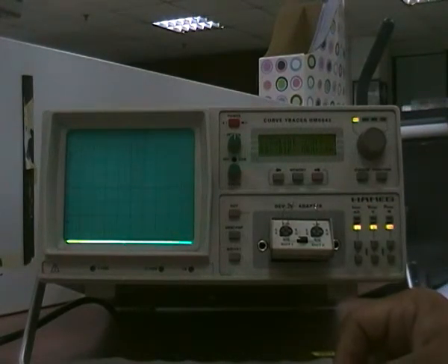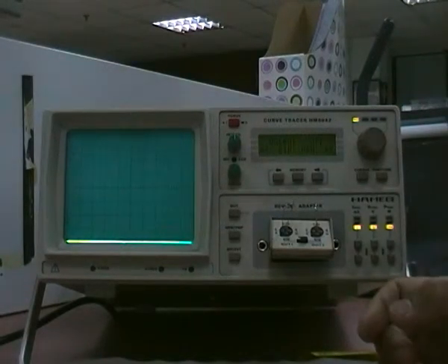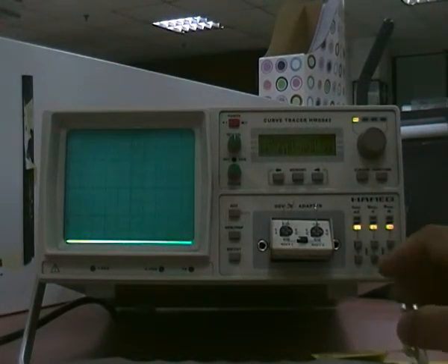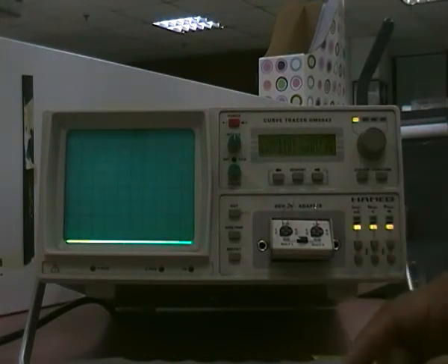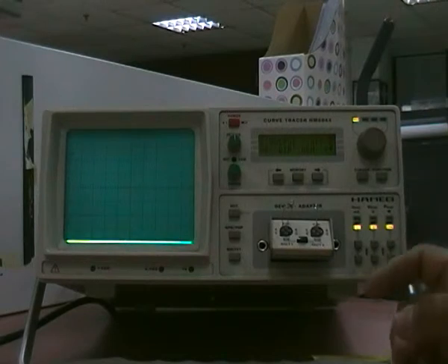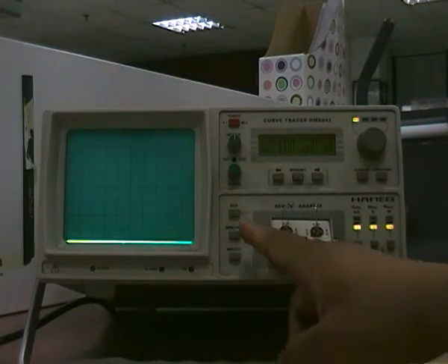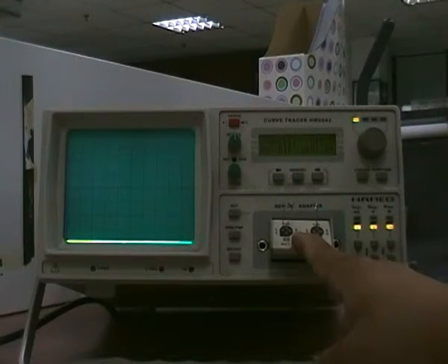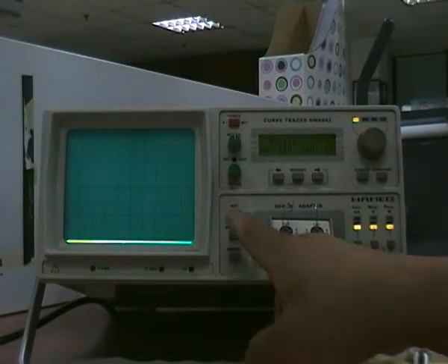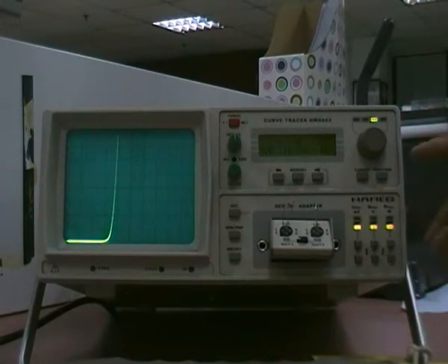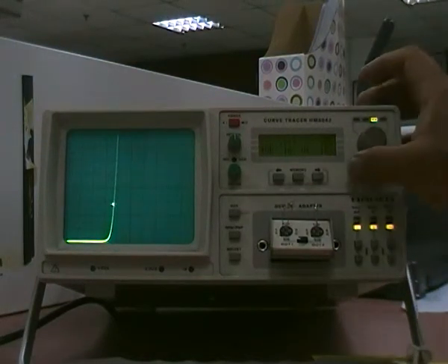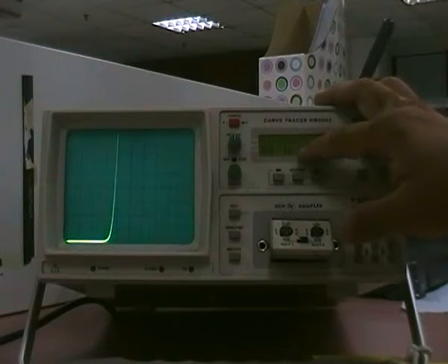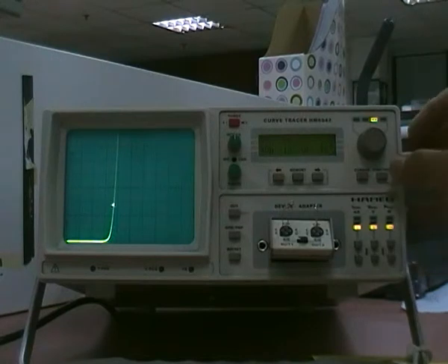I just want to measure whether the device is in good condition. What I know about the diode is the current is small, so I can put the power quite small. I just want to know whether the diode is in good working condition. Everything being set, I put it into device under test 2. Now what I need to do is to measure the voltage across the diode and the current across the diode.